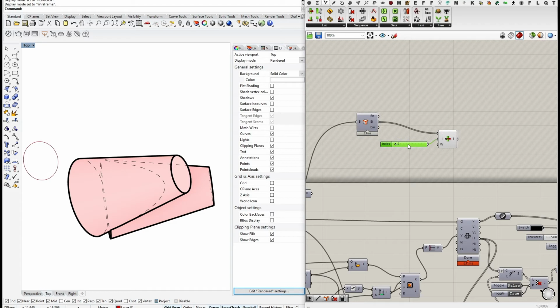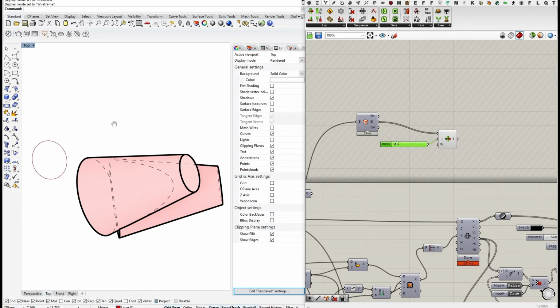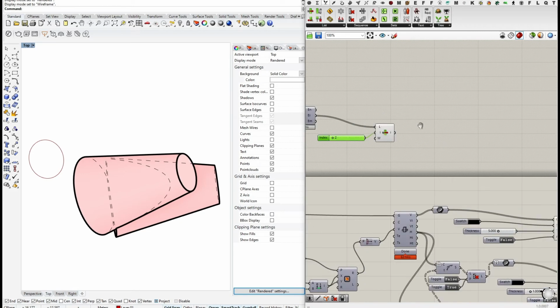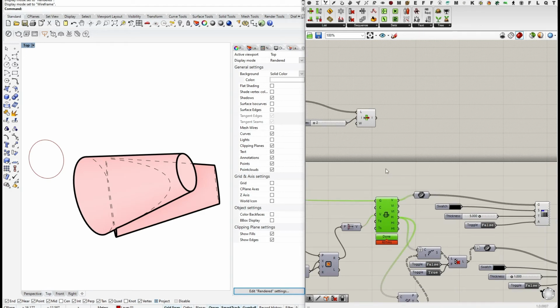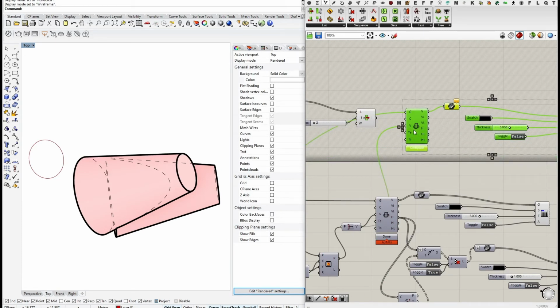So let's take this circle, for instance, and now we can copy paste our make2D component so that we generate automatically, like we have all the other settings already laid out before. So we copy paste this, and we're gonna use this geometry now for computing it. If you compute now, you will see you will automatically have this additional curve here.